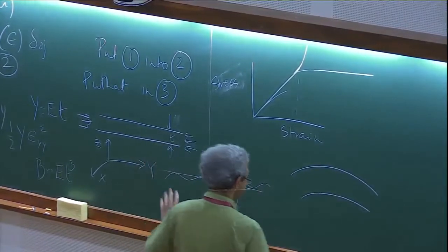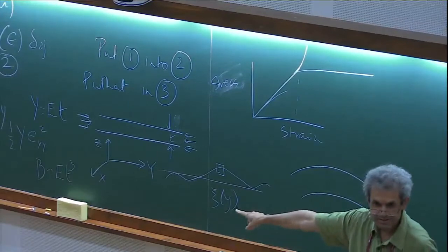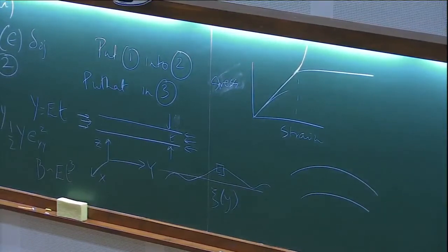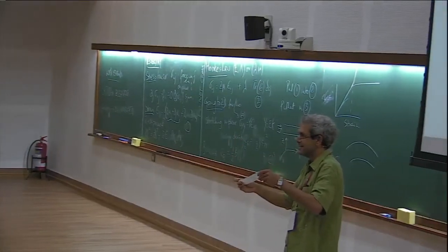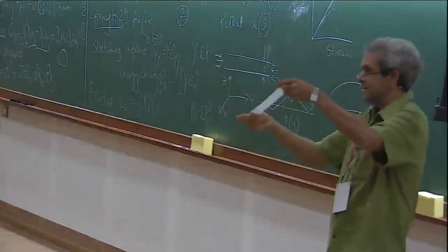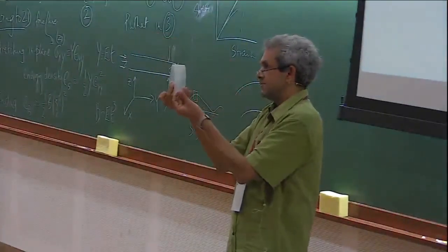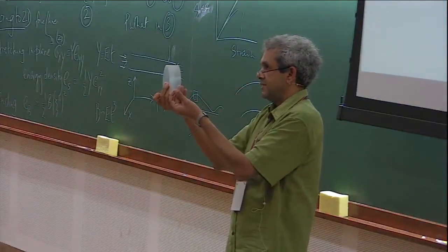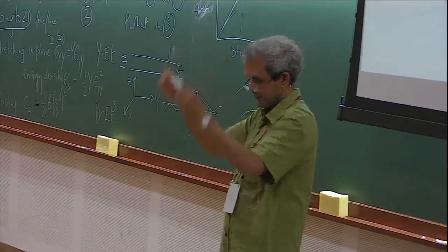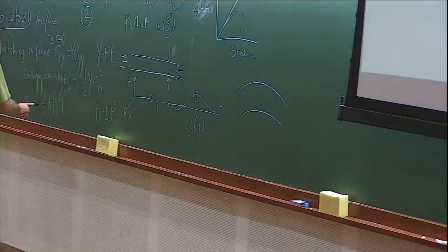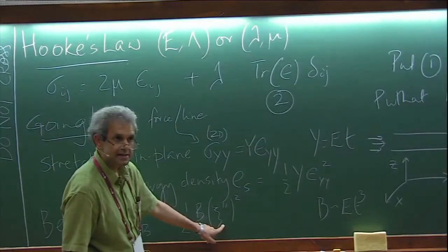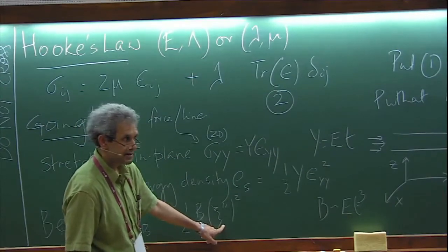Is it zeta? Maybe zeta. I asked to zoom in on this piece and look at this piece, and then you should realize for this piece, it pays nothing for slope, it pays nothing for, I'll make this a little bit better soon, but this was the argument we made yesterday. We pay nothing for slope, we pay nothing for displacement, but we pay for doing this. And we pay equally for doing this and for doing this. So the first level of hand-waving argument is that the energy density is proportional to the square of the second derivative, the curvature.